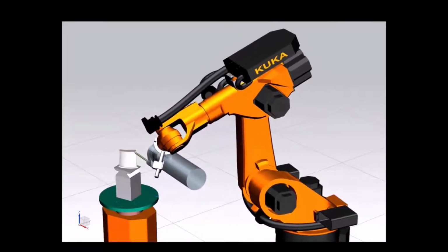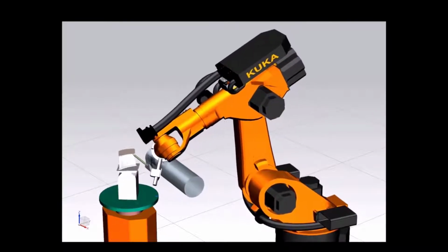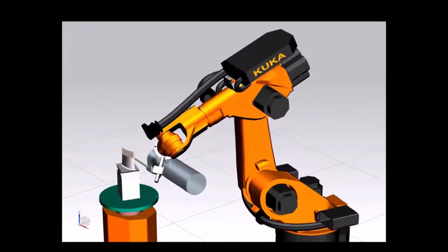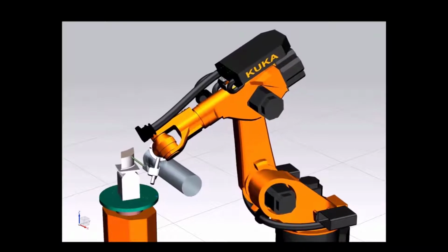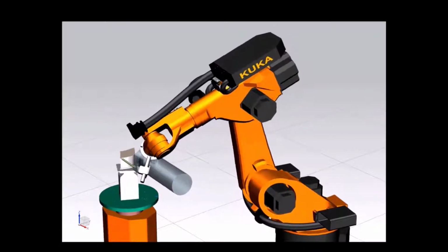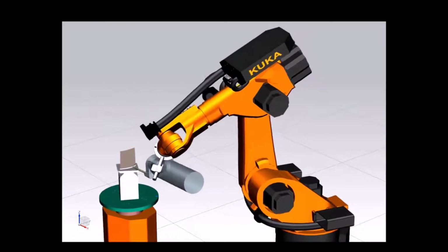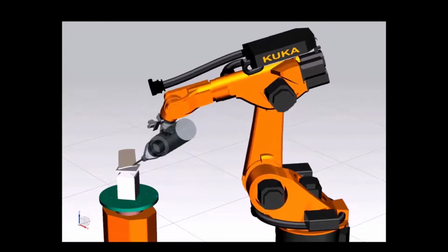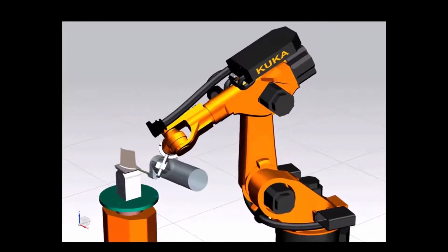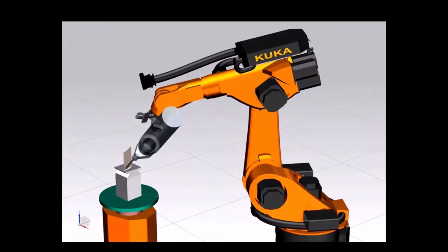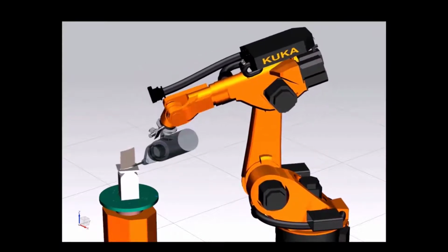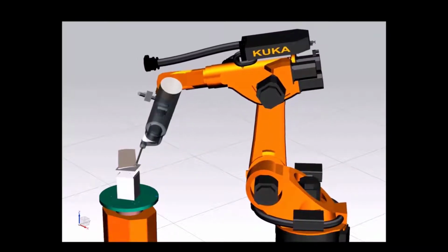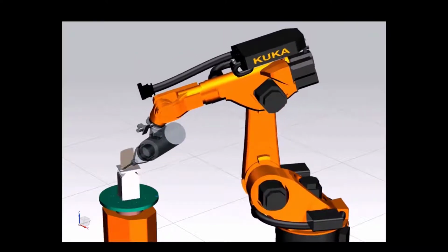The generic NX animation is a pure kinematic visualization of the toolpath geometry, which does not capture the motion speed. Several machine parameters defining the kinetic capability of the KUKA robot are not included in this simulation. Therefore, the timing of certain moves is unrealistic. The true robot motion results from combination of the true machine parameters with the output of the NX post-processor for the KUKA robot language KRL. Details of approximate positioning or flyby motions, for instance, cannot be predicted at this level by NX.